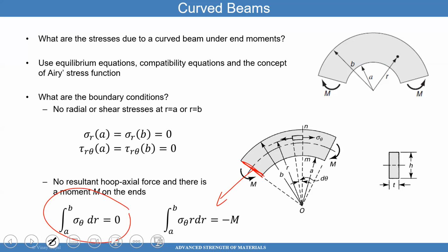So the question, I believe, is: if there's no axial force, how are we accounting for the variations of sigma RR, sigma theta theta from A to B? Not each of them, but the totality of that. It's not giving a resultant force in that direction, in this direction.